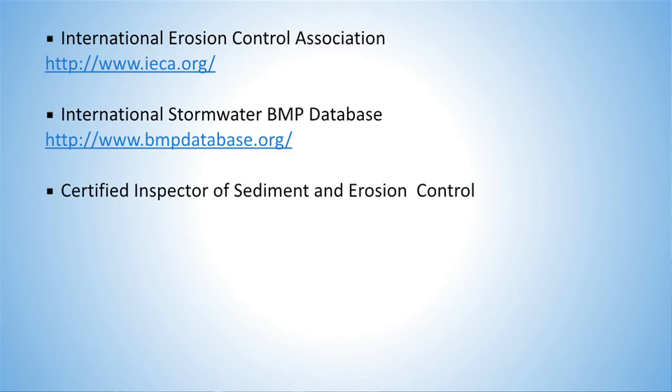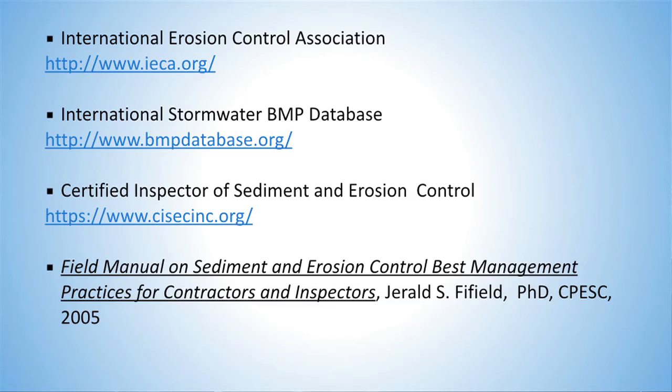Certified Inspector of Sediment and Stormwater Erosion Controls, CISEC. It's a good organization, provides some good training for that. Dr. Jerry Fifield's Field Manual on Sediment and Erosion Control BMPs for Contractors and Inspectors is a wonderful resource. Nice little book. It's printed on paper that can get wet. Keep it in your truck, keep it in your backpack for inspections. Little one sheet, cut sheet kind of information. It's a great resource when you're trying to explain to somebody how to go build something. You don't have to try to draw them a picture. You turn to that page and say, I want you to build this flow interceptor. I want you to build this check dam.